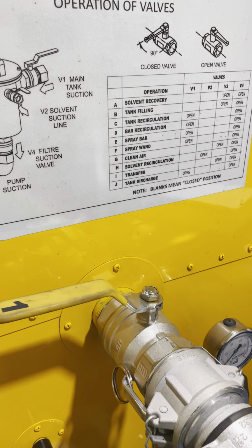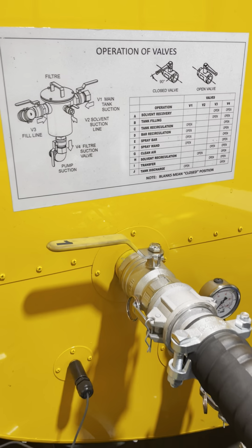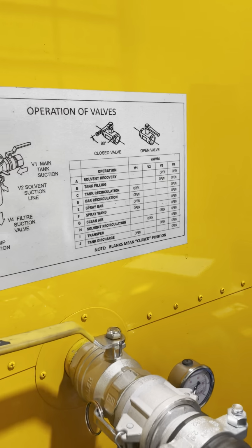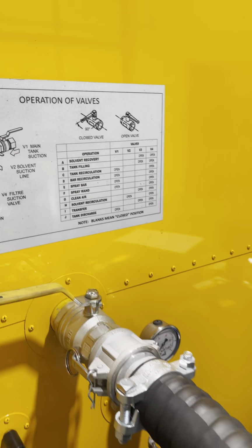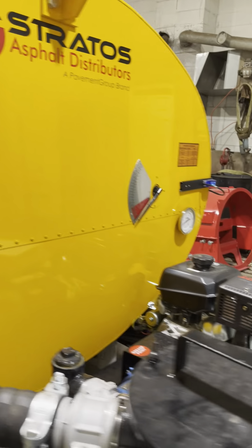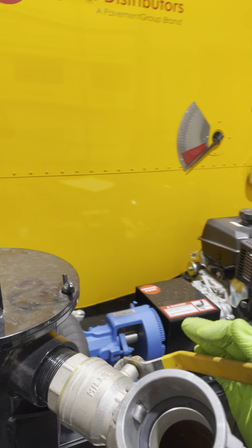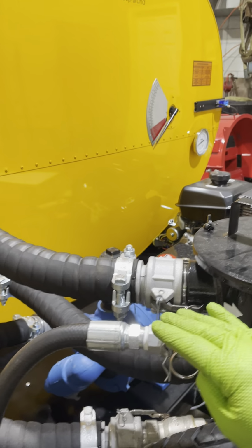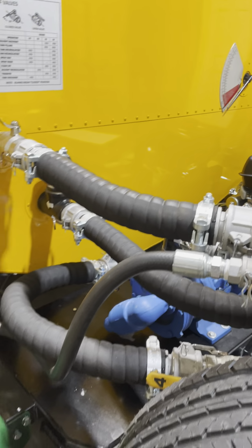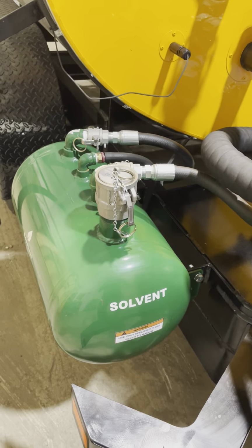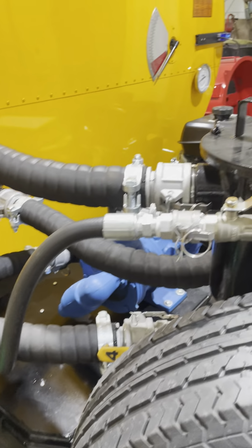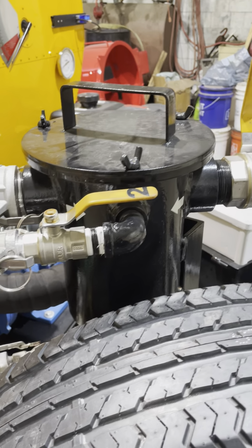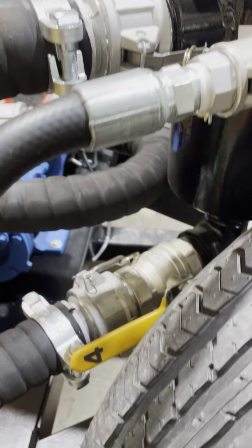We're not going to bring any material into the system. We're cleaning out now. Valve 2 will be open. Before you do that, you need to close valve 3, which was your previous operation of clean air. Now that you've opened valve 2, it starts bringing solvent from the tank into the strainer basket, starts cleaning out all that stuff, passes down through the strainer basket,